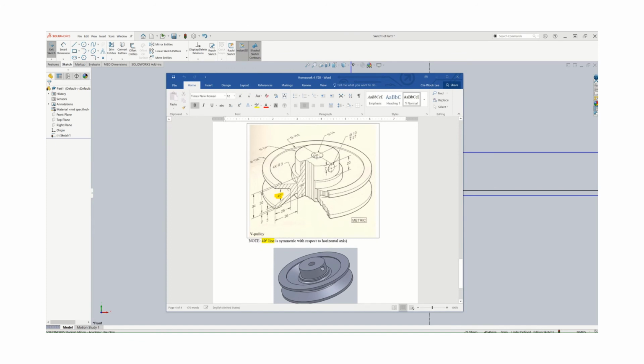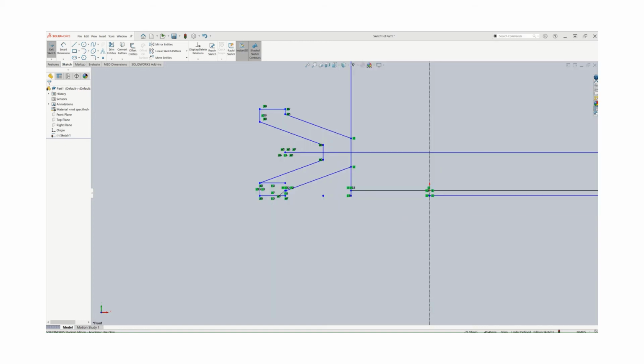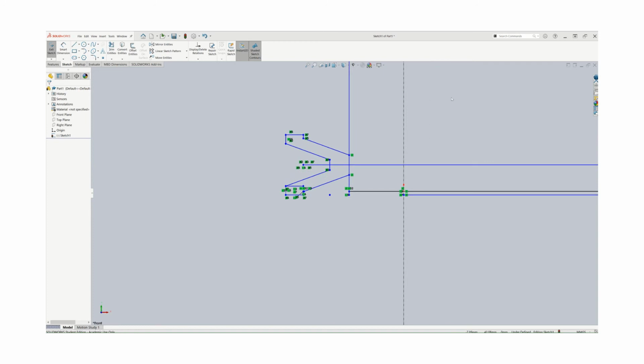Then starting from here, I have another, the cylinder, so I will have another line offset. This time this diameter will be given as 54, so the center line, the rotation axis, has to be offset by 27, and you could do it in a similar way to what we have done. So again, offset this line by 27, and that is going to be in the opposite direction. So that's one of the elements you have, and that's what we need.